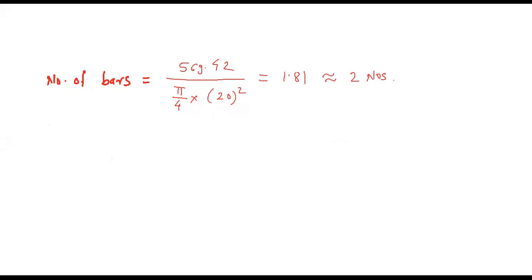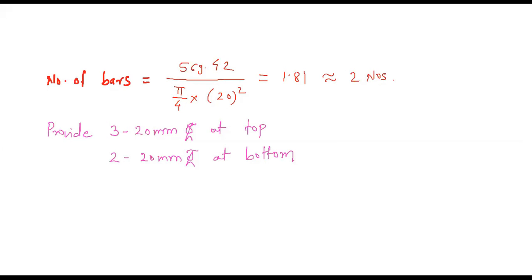So we can summarize this. I can write over here: provide 3 bars of 20 mm diameter at top and 2 bars of 20 mm diameter at bottom.